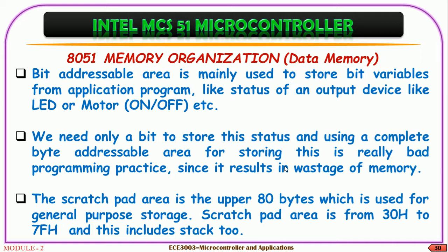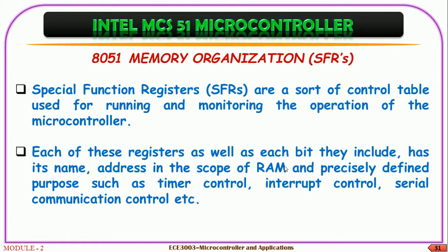The scratch pad area is used for general purpose storage, and it is from 30H to 7FH, and it includes the stack too. Special function registers are a sort of control table used for running and monitoring the operation of the microcontroller. Each special function register, as well as each bit they include, has its name, address in the scope of RAM, and a precisely defined purpose such as timer control, interrupt control, serial communication control, etc.